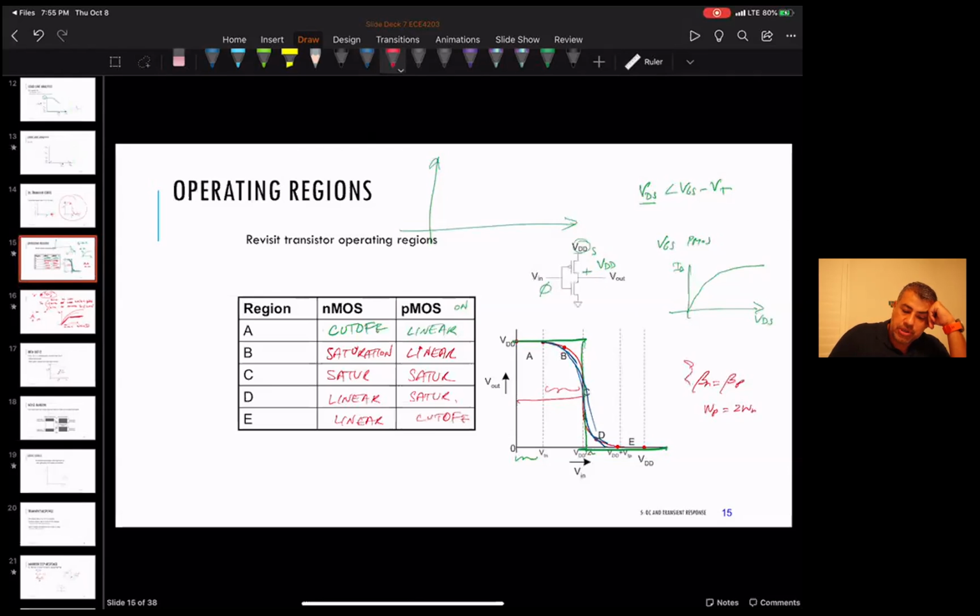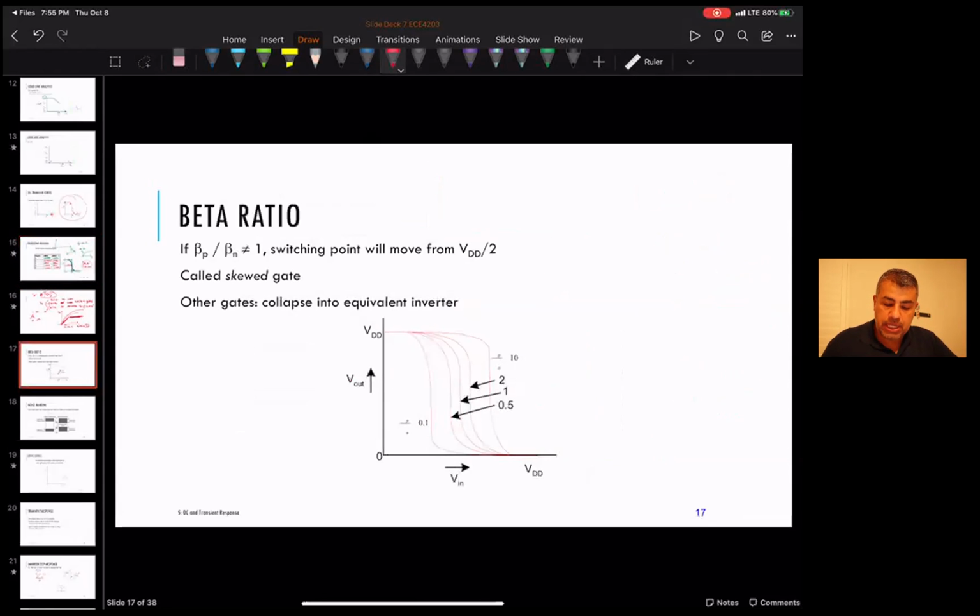These were assumptions when we started. So this switched right at the halfway point. Right at the halfway point, the currents were exactly the same, and the drain source and VGSs were the same, right? But this doesn't have to be the case. If you change those ratios, you start moving around where this shift happens, where these regions happen.